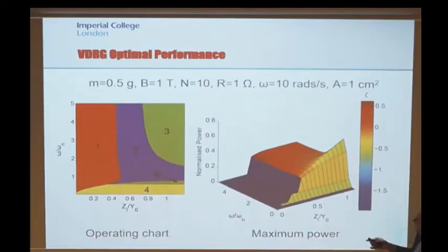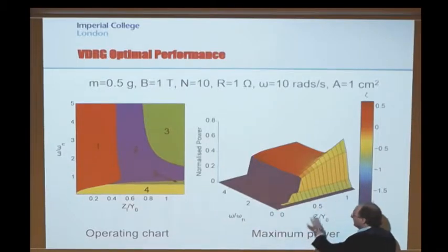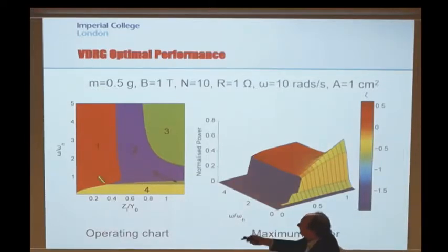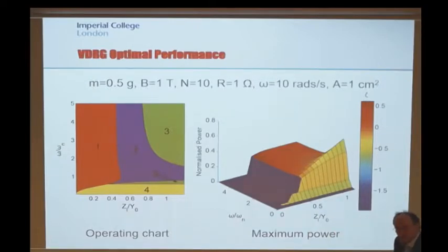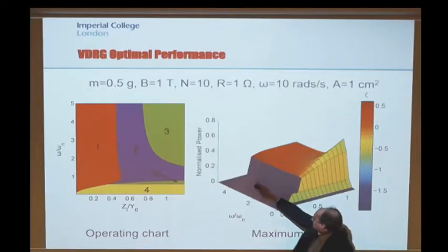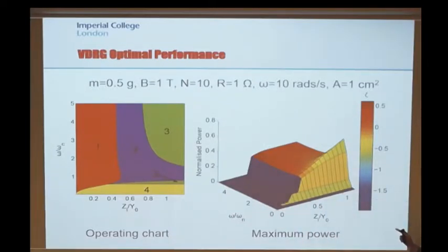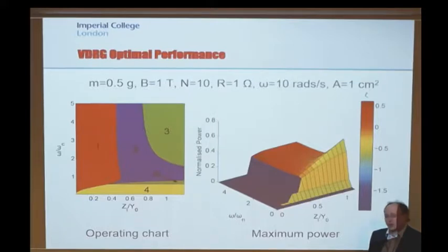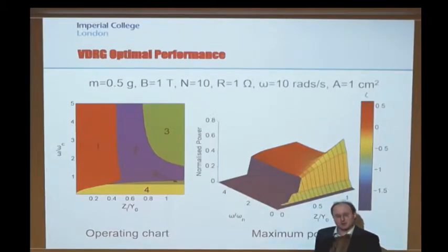So effectively what we did here was we looked at every aspect of operation of these devices based on how close it's operating to the resonant frequency and how big it is compared to the vibration source that is powering it, figured out the different operating modes here for what constraints apply in different regions of operation, and figured out the maximum power that can be generated. For this region here where no power is being generated in this particular scenario, for the particular set of practical constraints that were placed into here, we couldn't generate power here because we couldn't achieve a damping force that was big enough. Effectively what's happening, the device here, ZL, is very small. As the device is smaller and smaller, you need more and more damping force, and you get to the point where you can't realize a damping force which is big enough, in which case that meant that from a practical perspective we weren't able to generate power here.